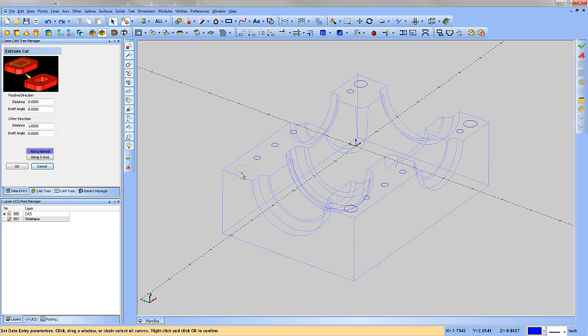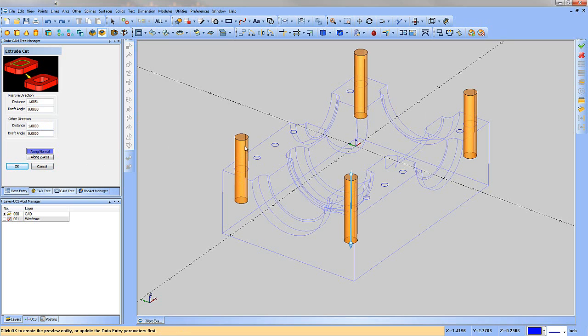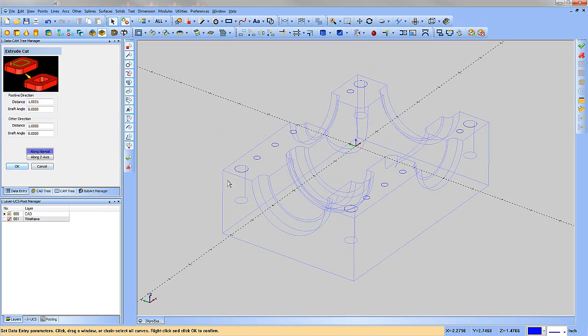Radius. We're going to pick the larger of the 2 holes, and with the Pick Match Radius function, it picks the first hole as that radius and then picks any radiuses that match it. For this one, we want to make sure that our distance goes down 1 inch. So when we hit OK, we want to be in the part 1 inch. But remember, if it does go up above, it's not hurting anything. It's going to remove this anyway. So even if we're 1 inch high up here, we just hit OK, and it's going to remove those holes.